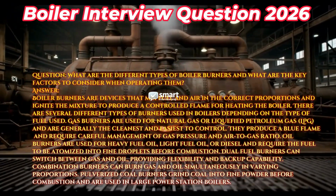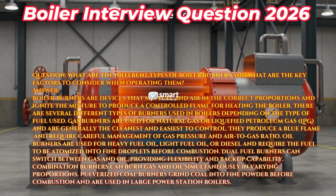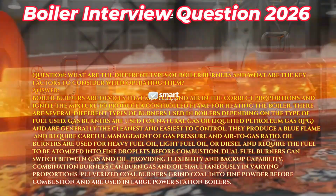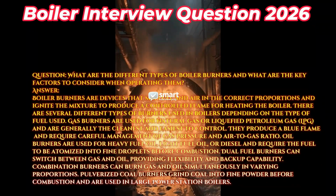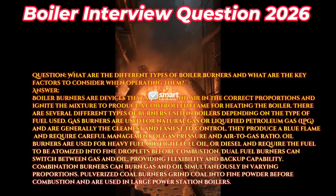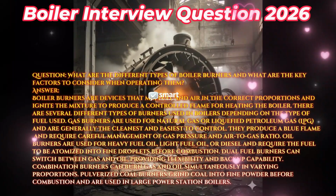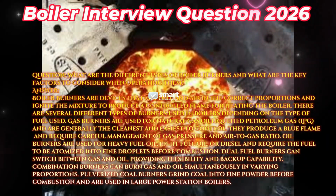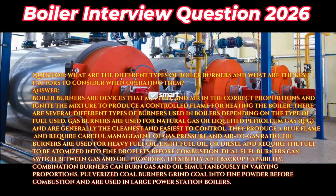Oil burners are used for heavy fuel oil, light fuel oil, or diesel and require the fuel to be atomized into fine droplets before combustion. Dual fuel burners can switch between gas and oil, providing flexibility and backup capability. Combination burners can burn gas and oil simultaneously in varying proportions. Pulverized coal burners grind coal into fine powder before combustion and are used in large power station boilers.